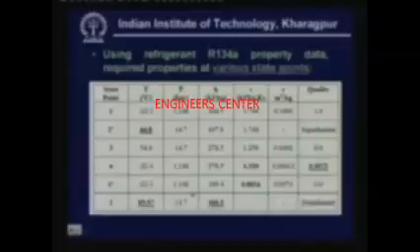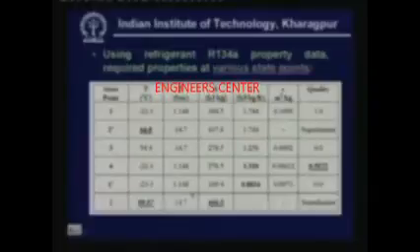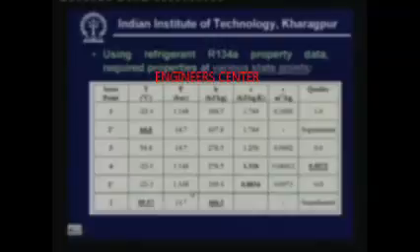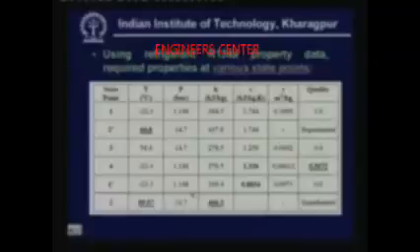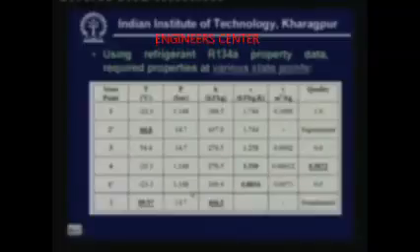So, if you use this information from the p-h chart or from a refrigerant property database, you find that enthalpy is 384.5, entropy is 1.744 and specific volume is 0.169. Similarly, for point 2 dash, which is the exit of the isentropic compression process, we know the pressure, 14.7 bar, and the entropy, which is the same as at point 1, that is 1.744. From the pressure and entropy, we find the rest of the properties, that is the temperature and enthalpy.